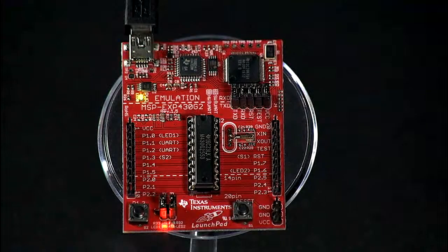The MSP430 LaunchPad kit includes an optional 32 kHz clock crystal that can be soldered onto the board. The board as is allows signal lines X in and X out to be used as multi-purpose I/Os. Once the crystal is soldered in place, those lines will be a digital frequency input. Please note that this is a delicate procedure since you'll be soldering a very small surface mount device with leads that are 0.5 millimeter apart on the LaunchPad.